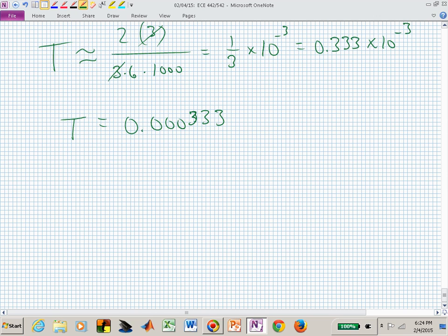Right now, just sort of accept it and say, okay, it's 30 times the bandwidth that we're using for a controls setting. And you could use something else. If you said, I can't sample that quickly, then you might say, let me see what happens if I sample at 10 times the bandwidth, and then see if that gives you acceptable behavior in your particular system. Right now, that's just something that we're starting with, and we will just use for now.